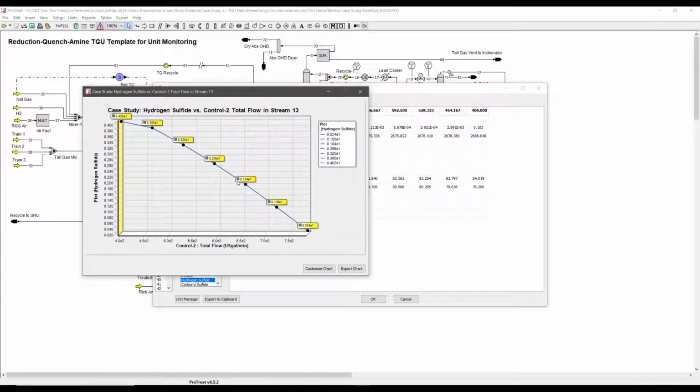We can also see that if we drop the solvent circulation, the TGU recycles less acid gas and is richer in H2S, about 5% rate. Because both of these outcomes open up room in plant capacity, they were considered worthy of trying in operations. The plant dropped rates successfully to 525 GPM without having to trigger a change authorization, which was worth several hundreds of thousands of dollars in sulfur capacity benefits.